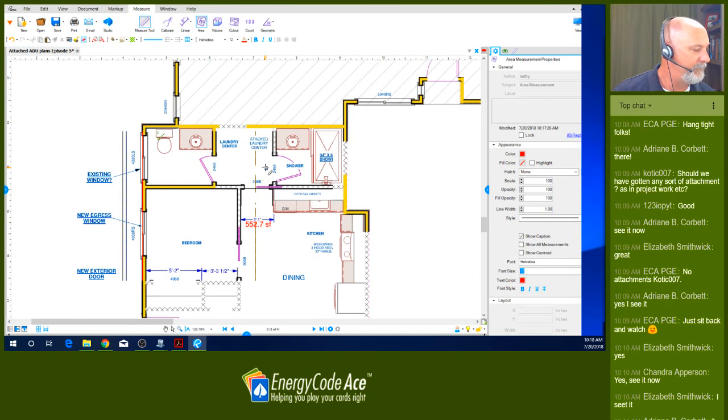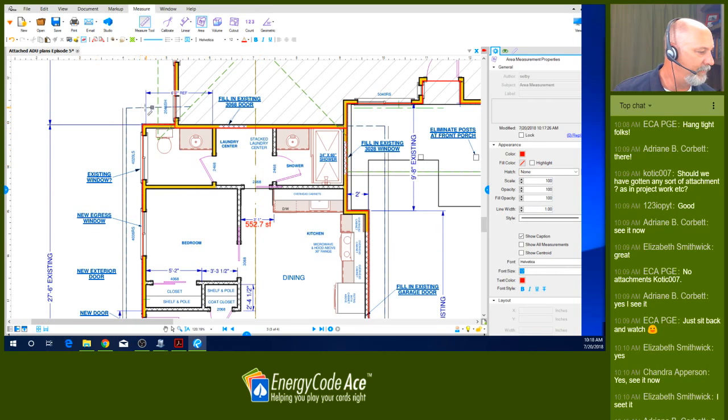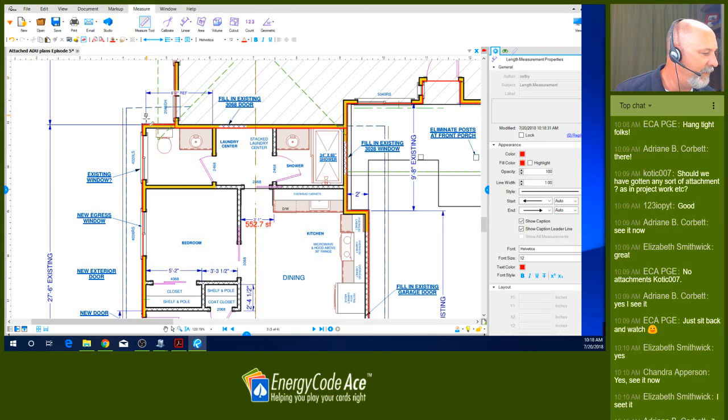Now, we've got some back wall area, so just keep an eye out for areas in the plan that may not be dimensioned. So in this case, we've got about a 3-foot wall here and a 2-foot wall on this side. So we've got 5 feet of rear wall, which is facing north. So we've got 45 square feet of wall that we need to account for. But as you can see, there are no windows or doors in that, so we don't need any openings.